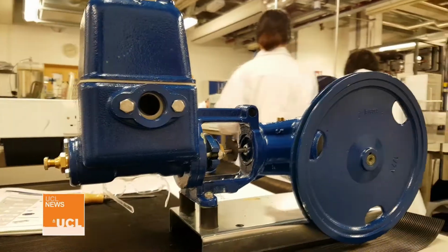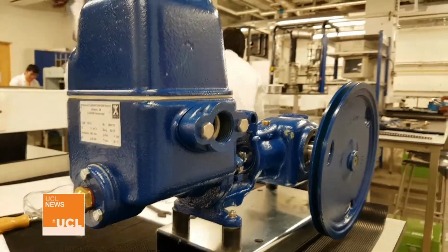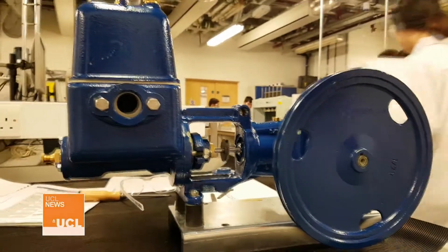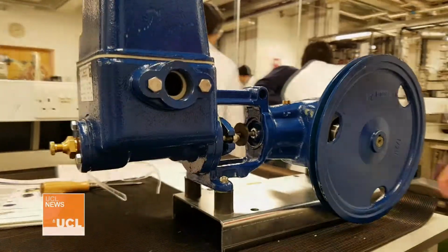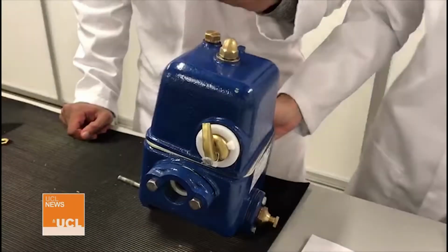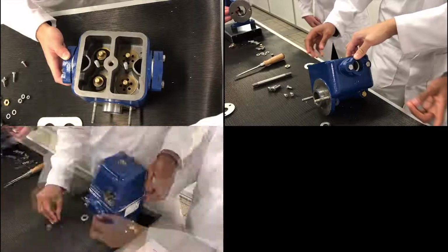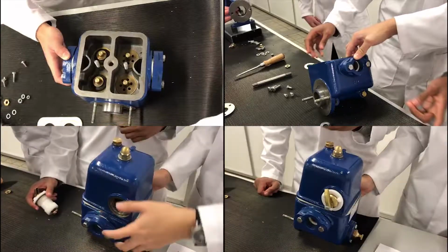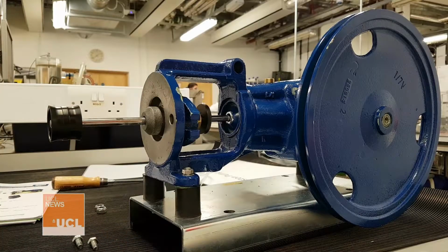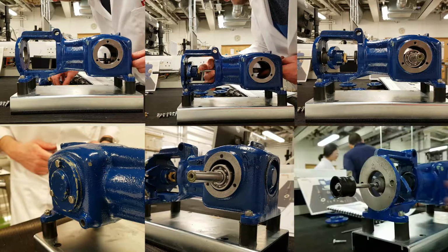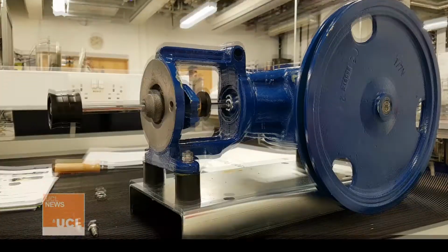The purpose of the piston pump is to move fluids. A piston pump may be single-acting, where fluid only flows out of one end, or double-acting, where fluid flows from both ends. For the pump housing, the main assembly components are the intake and pressure valves, straight flange, air chamber, stud bolt and seal, and the membrane safety valve. For the gearbox, the main components are the piston rod, packing gland, crankshaft, bearing and gearbox covers, and the duo piston. We finish by connecting the gearbox assembly with the pump housing.